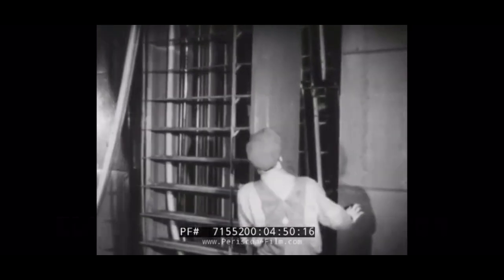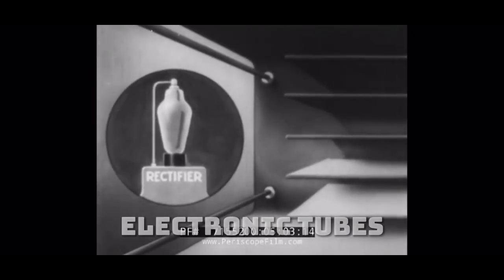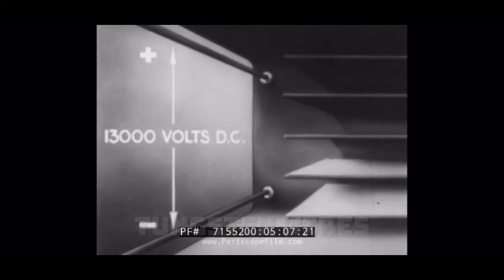Still another example of electronic rectification at work is the Precipitron, a device for cleaning air electrostatically. This diagram explains how the Precipitron works. The rectifying property of electronic tubes is used to apply a potential of 13,000 volts DC to tungsten wires and 6,500 volts DC to collector plates.